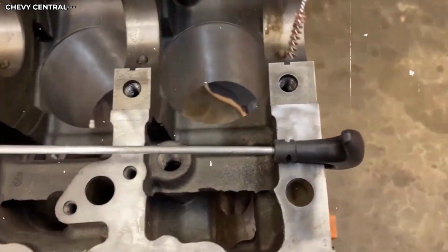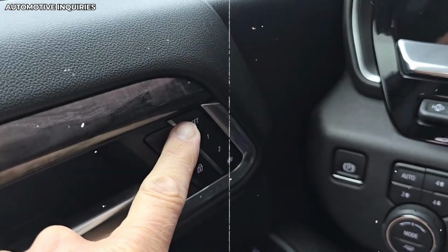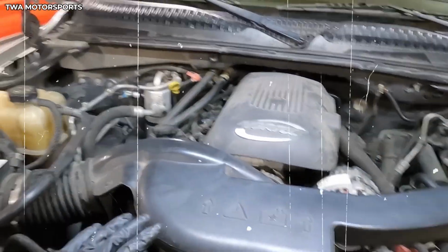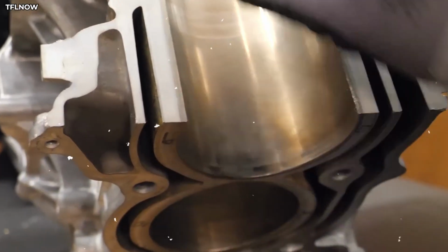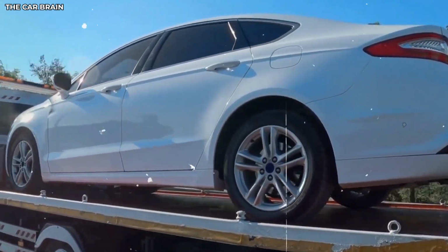One critical detail most owners don't understand is the difference between a throttle body reset and a complete adaptive learning reset. A throttle body reset only clears learned idle position data. A complete adaptive learning reset dumps all learned driving data, forcing everything to return to factory baseline calibration.